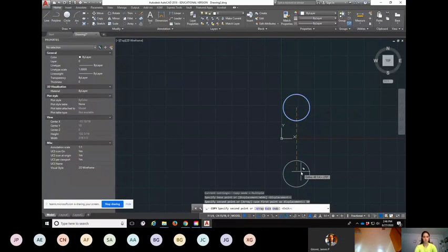All right. Now, I can copy that any which way I want to and still keep it on that ortho mode and keep it on a 180 or 90 degree angle. See how it won't let me move it toward the middle there? That's because it's locked in ortho mode. So I hit F8 again, turn that off, and it'll let me move it to different angles.